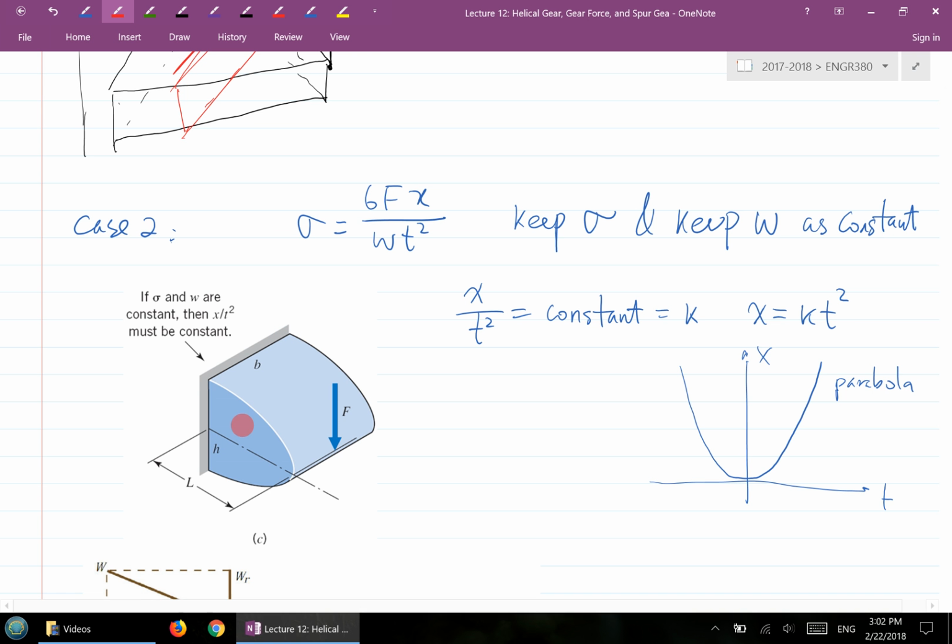So if you cut a cross section over here, anywhere, right, you get the same W. Okay, you get the same W, and the thickness T will be different, of course, depending on where you do the cutting. Okay. So these two cases will give you the so-called constant strength, or essentially a constant normal stress, basically. Okay. It's the second case that we actually will make use of for our gear tooth stress derivation, okay, stress analysis. Everything okay? So far so good?